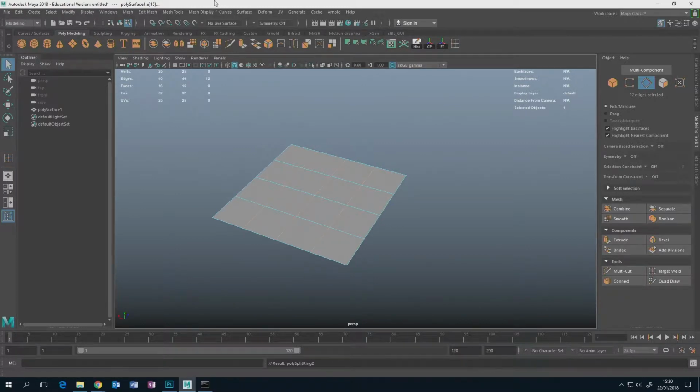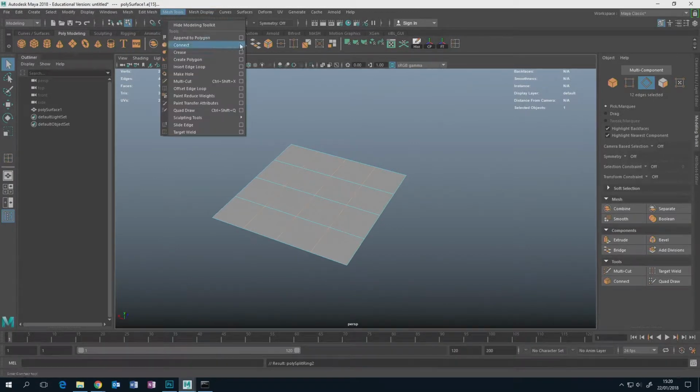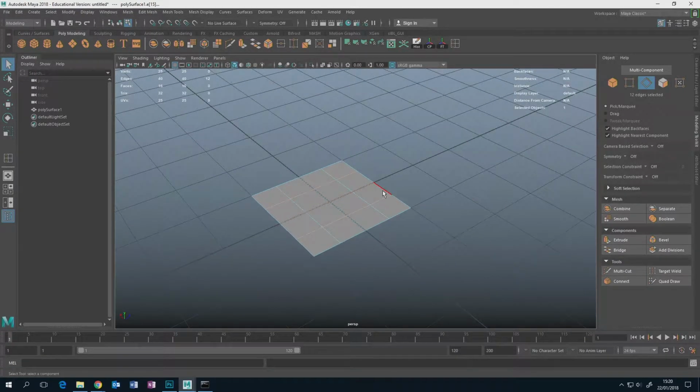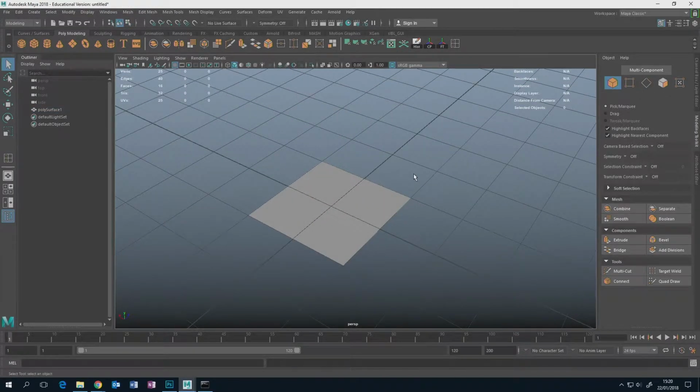The way you do that, there's a couple of things actually. This ties in with a couple of very frequent commands. As you're modeling, each thing you do gets remembered in the history, like it's remembered the split here, and how I created the plane. Every single vertex, if you just nudge it once, that's a new operation. So every now and again you want to delete the history. Deleting by history is normally Edit, Delete by Type, History, or if you want to do it for everything, Delete All by Type. To speed this up, we can add that as a button onto the shelf.